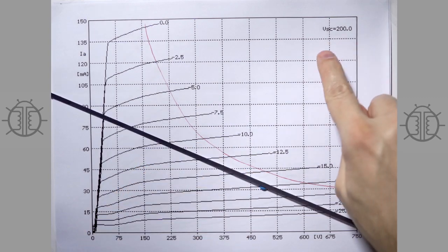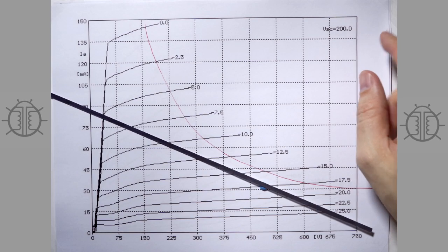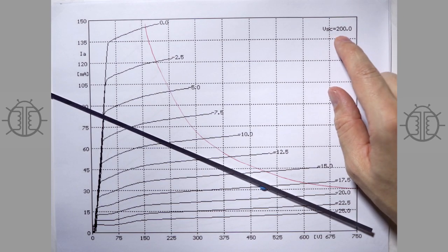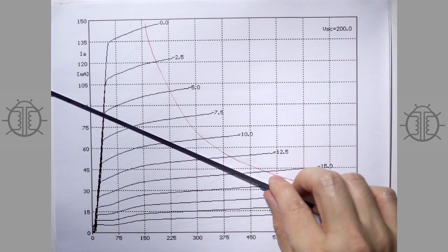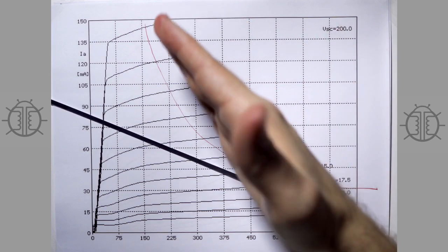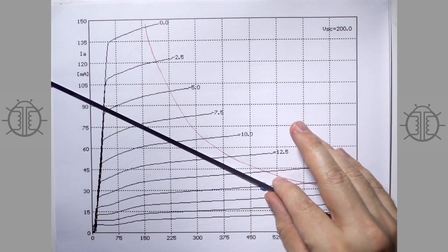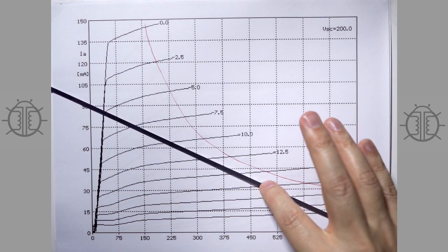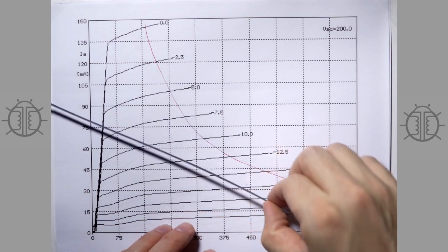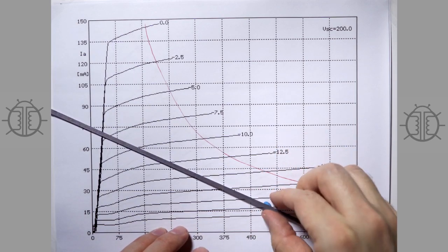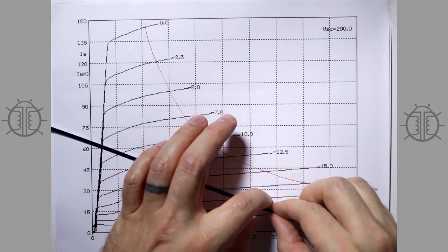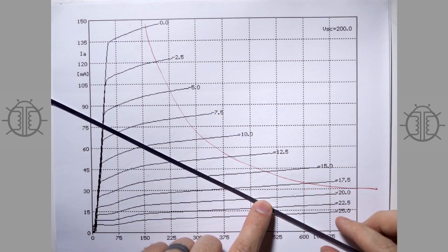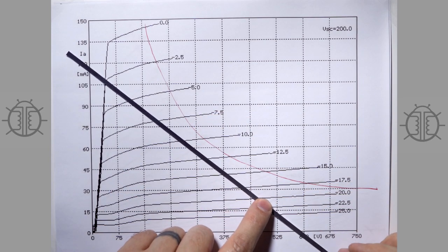So obviously this is pentode operation: you connect the screen grid to a fixed voltage, in this case 200 volts. And I think that's in the data sheet. So there you go. This is what the curves for a 200 volt screen grid 6L6 look like. And we can pick an operating point here. We know we're going to go AB, so maybe we should pick a lower current here. That way we'll go to AB a little bit sooner. So something like, maybe even like this.